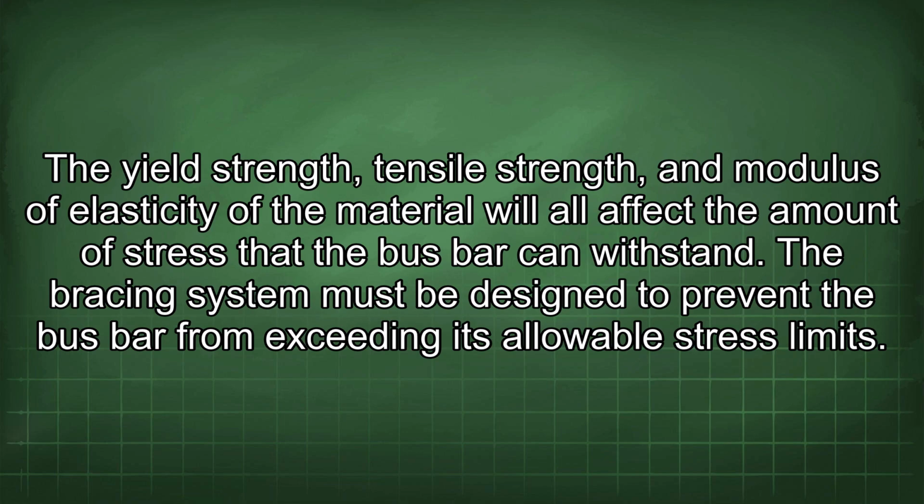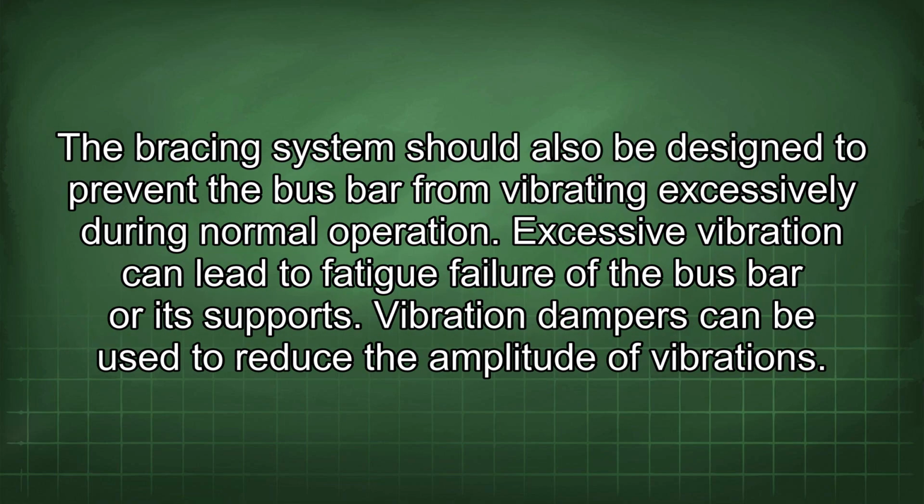The bracing system must be designed to prevent the bus bar from exceeding its allowable stress limits. The bracing system should also be designed to prevent the bus bar from vibrating excessively during normal operation. Excessive vibration can lead to fatigue failure of the bus bar or its supports.